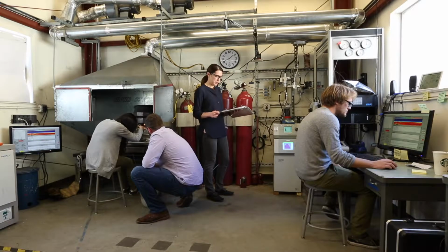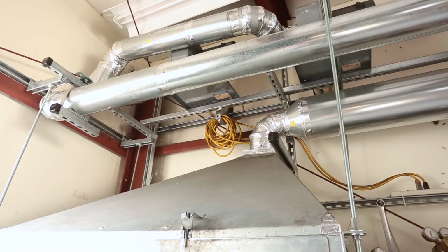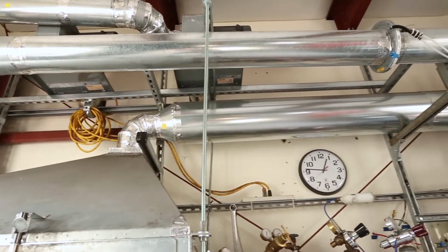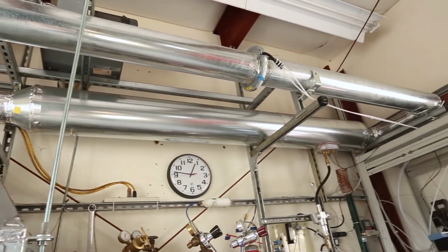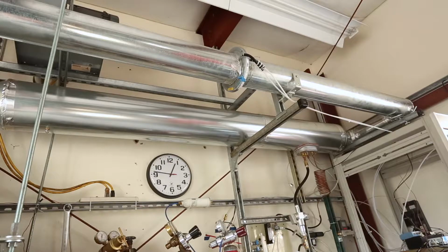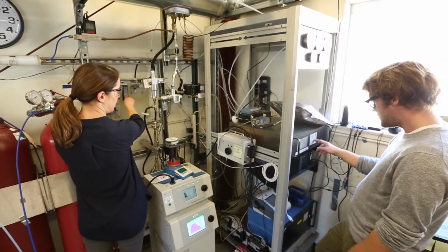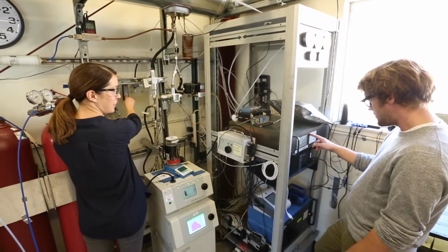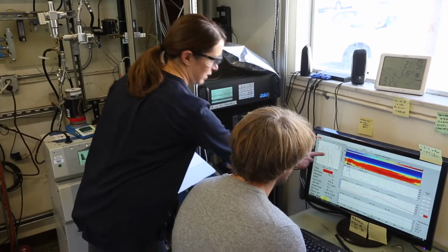Connecting real-time aerosol instruments to a cookstove testing system has several significant challenges. These challenges stem from the fact that the primary dilution tunnel can contain emission concentrations that are hundreds of times higher than the ranges the instruments were designed to measure. Almost all high-quality aerosol instruments were originally designed with the measurement of ambient air in mind. Therefore, these instruments will give poor data or could even be damaged if they are subjected to the extremely high concentrations of aerosols present in cookstove smoke.